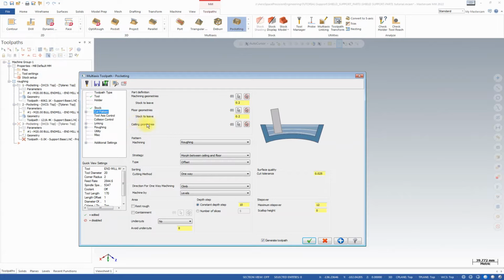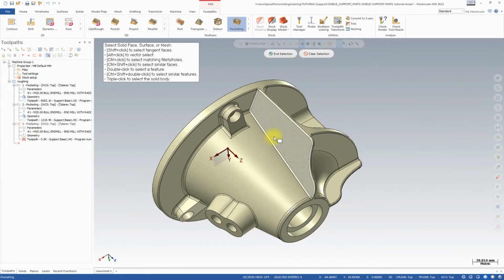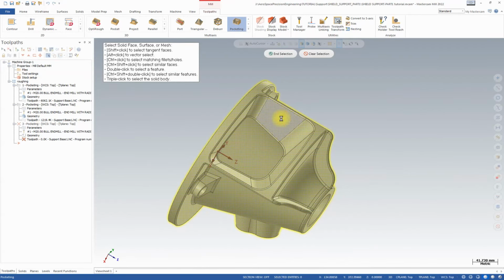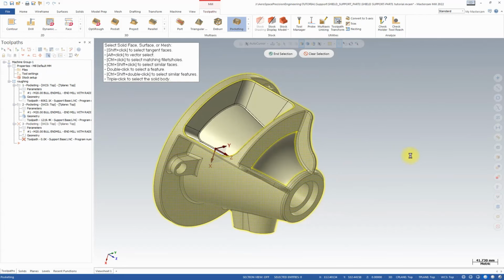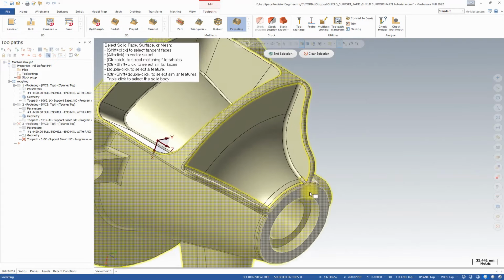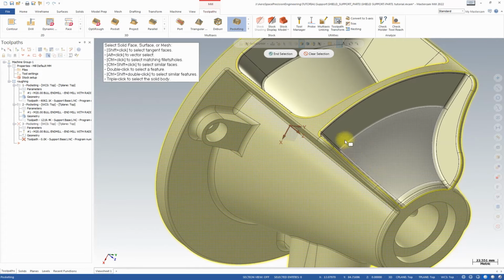to calculate the roughing operation. Now on the cut pattern page, I'm going to describe my part definition, and let's start with machining geometries. So I'm going to select the whole 3D model except those two pockets, except the closed pocket here, and accept this front open pocket. Double click. Oh, it doesn't work, so I have to manually select all the faces. I'm going to zoom out a bit. Okay, so I've got all these